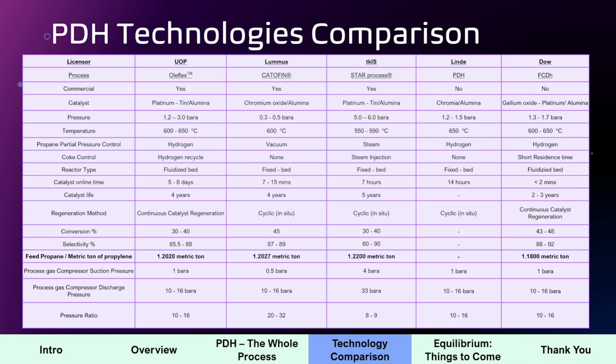In terms of absolute pressure, which is the total pressure and happens to be the pressure of propane, they pretty much operated at vacuum. And of course, because you're pushing conversion there, and the residence time is a matter of minutes, you can imagine how expensive those reactors are going to be, because you are swinging between regeneration and normal operation in a matter of 15 minutes. So it's a pretty tough service.